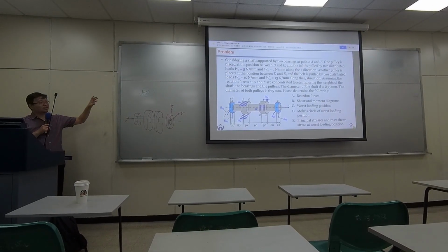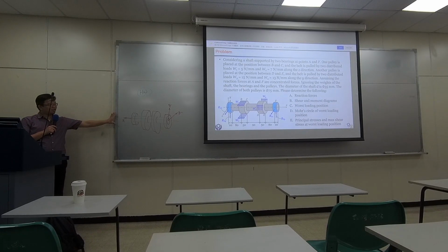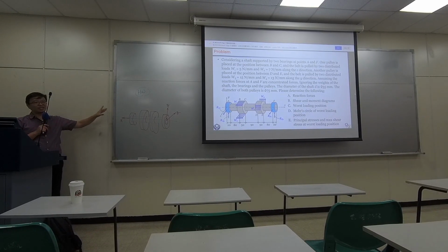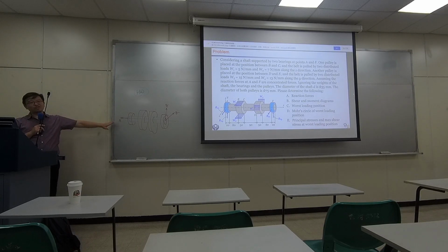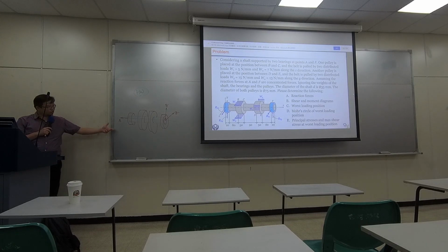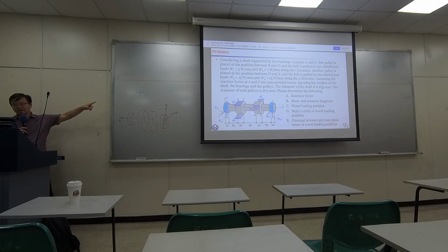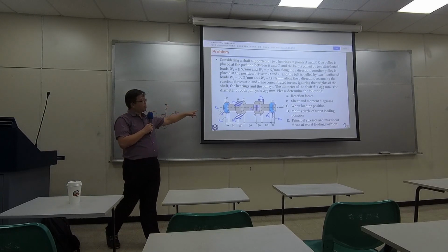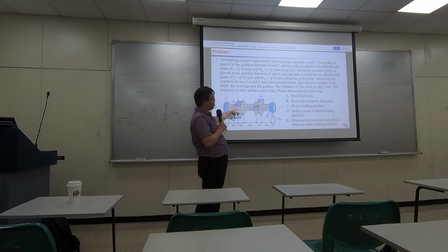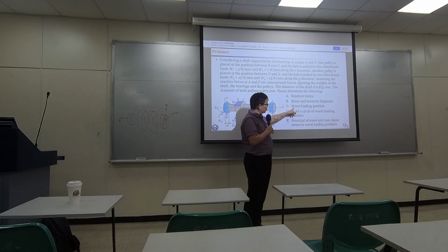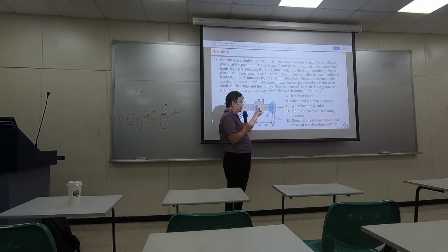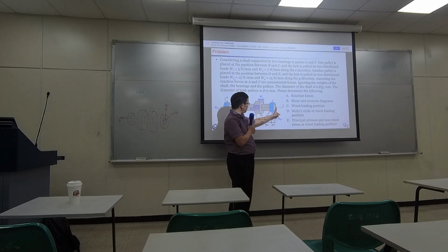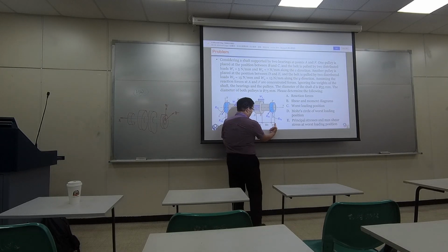Don't worry, I won't give a complex problem like this in the exam, because our exam only lasts for 1 hour. So it will be much simpler. But when you go home, I want you to experience the whole thing. First, compute the reaction forces, determine the shear and moment diagrams, and figure out the position with the worst loading condition. That will be somewhere here, exactly here, but with different coordinates, because your zero is right here. Your zero is right here, okay?